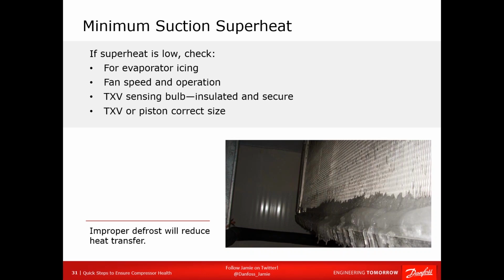I've seen all of these things, especially with TXVs where they use one TXV in multiple capacity systems. If they're installed right, everything's fine. Well, if the TXV has extra capacity, and a lot of times they do, if it's going to flood the compressor or flood the evaporator, it's just going to do it that much more. By the way, this coil, I've seen them get so bad where they actually crack and split down the middle. Scares the hell out of everybody.